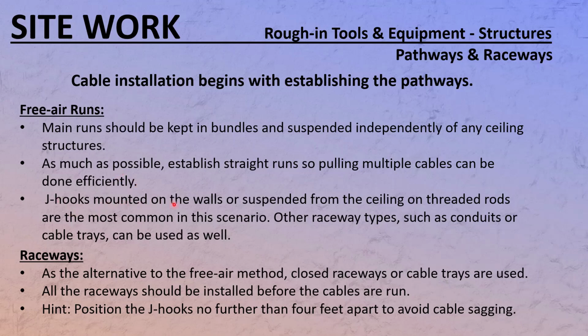J-hooks mounted on the walls or suspended from the ceiling on threaded rods are most common for this scenario. So J-hooks can be mounted in the ceiling or on the walls or suspended on threaded rods. We'll show you what those are. They're quite popular. Other raceway types such as conduits or cable trays can be used as well.